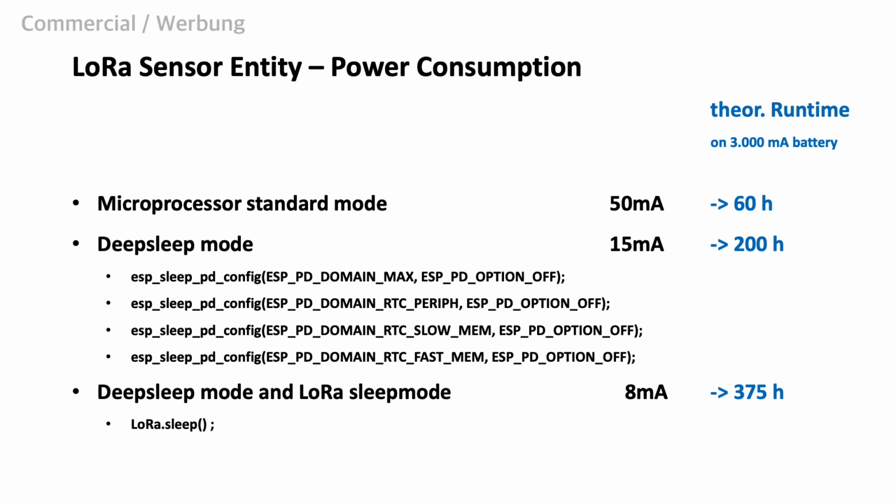The measurements for the board's power consumption can be done with a simple multimeter. But keep in mind that the accuracy will not be the greatest, because our microprocessor boards don't draw a constant current. It is rather bursty and with a lot of short spikes. But anyway, even if not very accurate, the results are giving us a good idea what happens. Of course, it would be better to use an oscilloscope for this, because we could see then the bursts and the spikes with it.